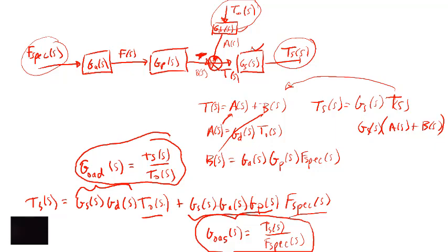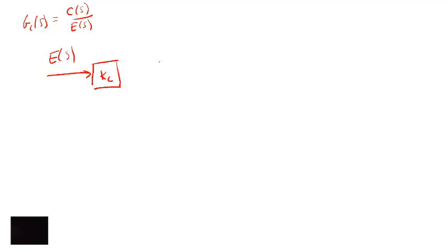There's a variety of ways that we can use that. We can talk about this with respect to PID control, which is something we'll go to later. The transfer function for a controller is going to be the output of the controller, the controller value, over the input to the controller, which is the error in the process. And again, the error in the process is just the difference between the set point and the sensed value. We'll come back to these things later. If we have an error, the algorithm for a PID controller starts with the proportional term, Kc. This is just a constant, or we could call this G, the transfer function with respect to the proportional term.